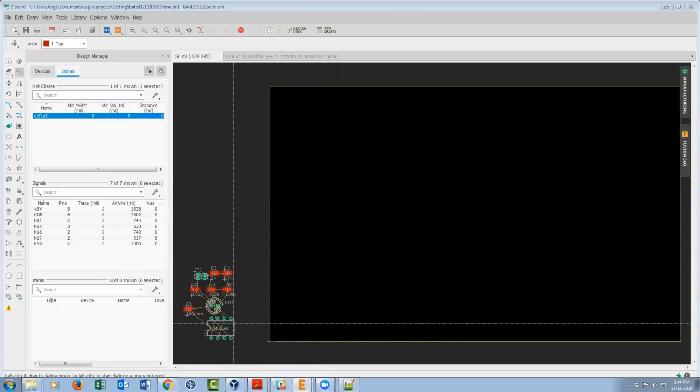If you catch it, if you realize it quickly, it's not too bad to recover from, but you don't want to be figuring out that you broke consistency 3 hours ago. A lot of times when it happens, it's because by mistake you closed the board and worked on the schematic, so the board couldn't catch up. But Eagle actually does a really good job letting you know when you have done that. Yes, and let's show that.